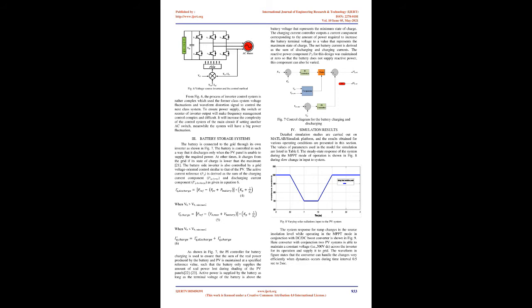Start P&O algorithm. Measure V(k), I(k). dP = P(k) - P(k-1), where P(k) = V(k) * I(k). Is dP > 0? Yes or no. Is V(k) - V(k-1) > 0? Increase PV voltage or decrease PV voltage. Update V(k-1) = V(k), P(k-1) = P(k).